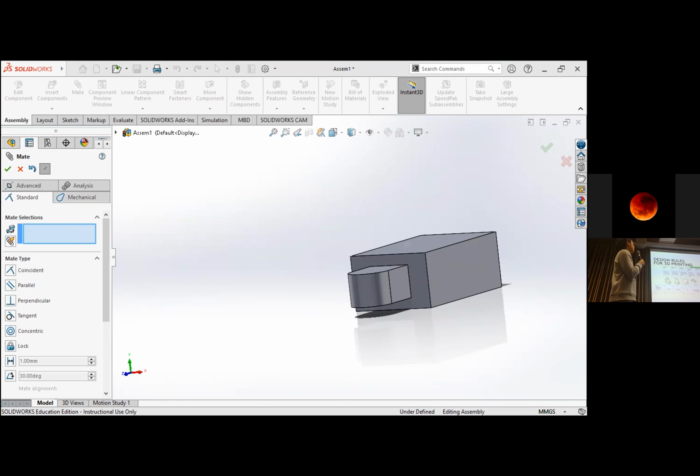The most important ones are such as for supports and overhangs, you don't want to go at too steep an angle because stuff will fall due to gravity. And also when you have parts that are connecting, you want to have a bit of a gap, otherwise they will not fit together. I recommend the gap to be 0.2 mm. And your parts should fit together decently if you have a 0.2 mm gap between, let's say, the key and the keyhole that you designed just now. Moving on.